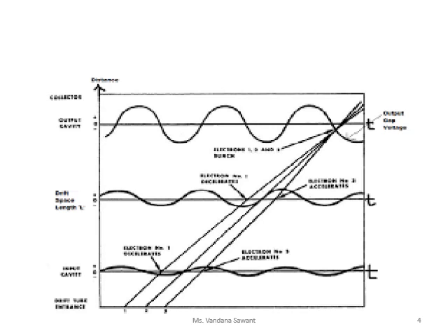They will get accelerated. They will reach the buncher cavity. In the buncher cavity, there is an input RF signal. That input RF signal will accelerate or decelerate the electrons, which results in velocity modulation. So velocity modulation results in the formation of a bunch of electrons. Now this bunch of electrons, when they reach the catcher cavity, travels through the length L, that is a drift-free space.